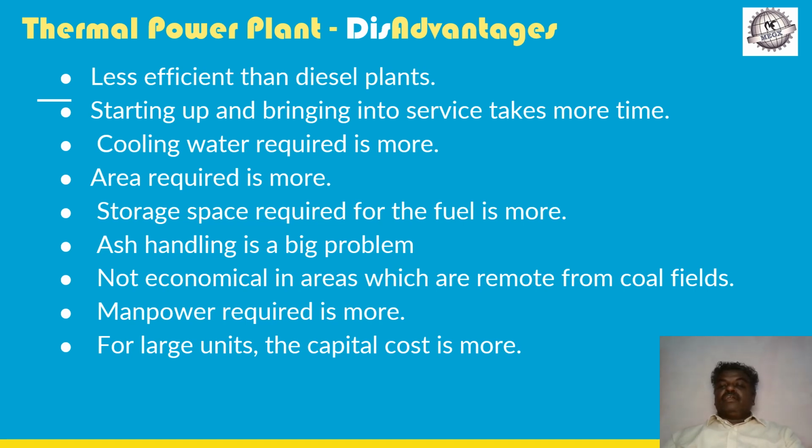And if the power plants are not located closer to the coal fields, they are not economical in the sense a lot of cost is involved in transportation of the coal. The manpower required is also more because there are many number of components, and for large units normally the capital cost is more.